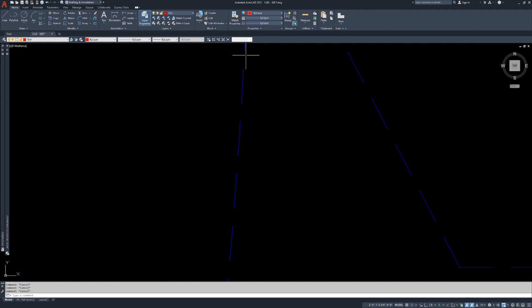So a hidden line is a dash and a space. Space, dash, space, dash. Now, way back in the day when we used actual pen plotters, where it was a machine that would literally pick up a pen into the carriage, slide over, and would draw like you would with a pen or a pencil. It was the coolest thing, and I'm from the days of old. The way that it would determine how to draw the line type, it would say pen up, so it's not touching the paper, space, pen down, draw the line, pen up, space, pen down. That's how line types work.